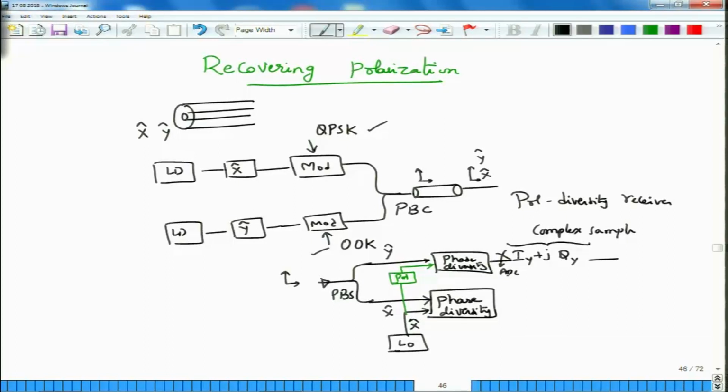Before the analog to digital converter, you have what is called an analog signal, because signals are varying continuously in time, or continuous time signals. Output of the ADC will be discrete complex samples, and you do the same thing even at the other end. So, you have an ADC running in the X branch as well. Usually these ADCs are synchronized to the same clock source. Okay, so that both are sampled almost at the same time.